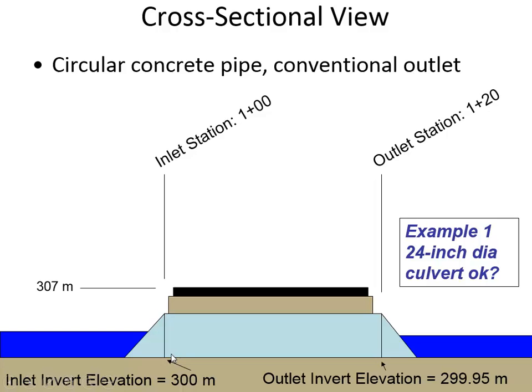One of the really important things is to know how high off of the channel bottom the roadway is. Why do you suppose it's important for us to tell the program the elevation of the roadway height? Well, you'd prefer that the water not get this high and start going over the road, but sometimes it's okay. They call it overtopping when the flow goes over the top.